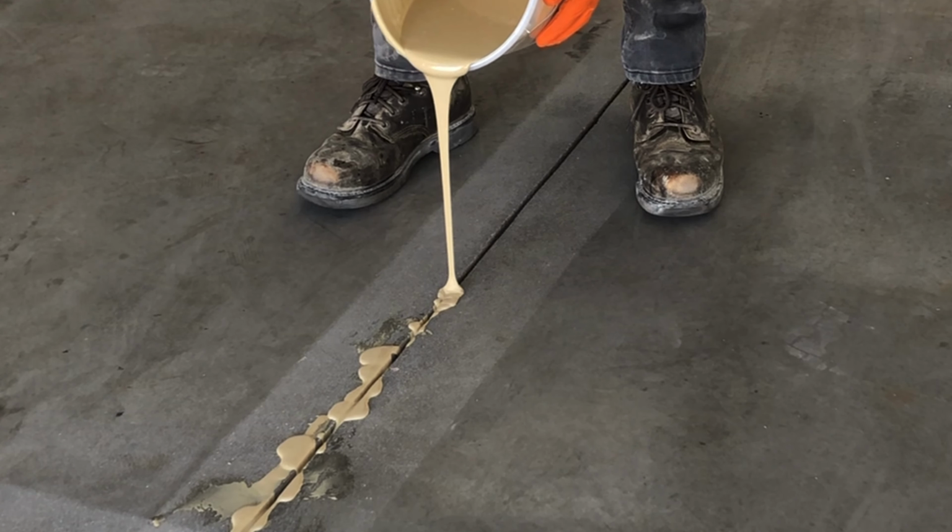Correct. I would say that the biggest word of caution for a contractor that is assigned to come up with a solution for a crack or a joint that has to be filled would be that they're competent enough to assess that joint or crack should be filled or can be filled. Because there is no way to guarantee future movement can be stopped, or that the slab may choose at some point, whether it's thermal expansion and contraction, whether it's sub-base integrity that's in question. It's very difficult to know those things. So I think the biggest word of caution for a contractor would be to assess the items that need to be repaired, but also that there's actually going to be a fix for that will provide a repair that lasts.